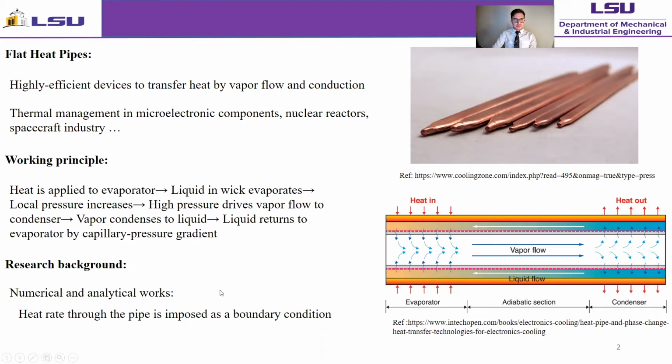There are numerous numerical and analytical works done on flat heat pipes. In most heat pipe models in the literature, the heat rate through the pipe is imposed as a boundary condition. Here, we solve the heat transfer rate through the heat pipe as part of the solution.